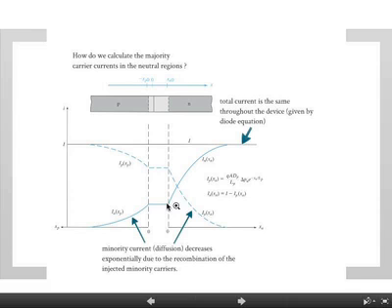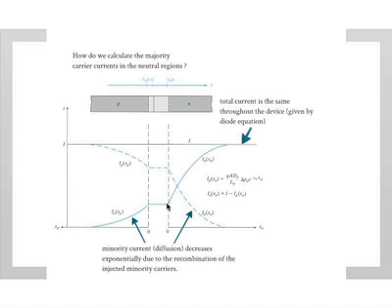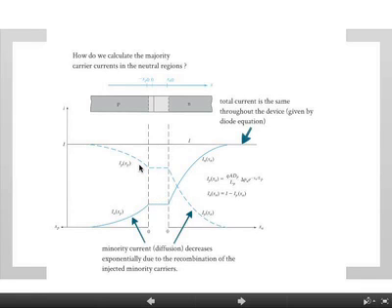Near the junction, within the junction, of course, the currents really don't change very much because it's basically drift. You get swept across. So let's ignore what's right in the depletion region because it's just the electric field. Nothing too interesting. But right outside it, it is the diffusion current. So this is the minority carrier current, electrons in the p-type material. It is diffusing and recombining. You have an expression which looks like that.